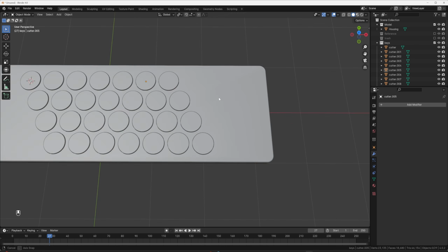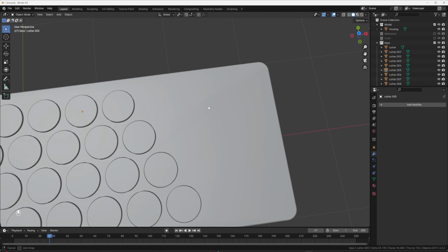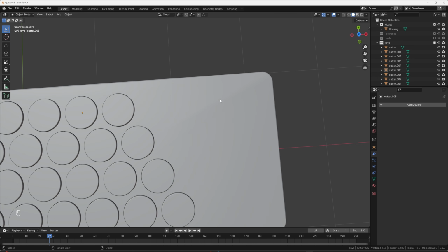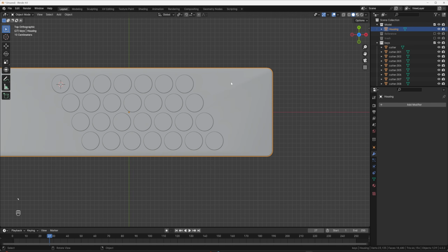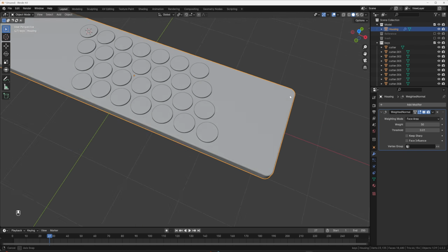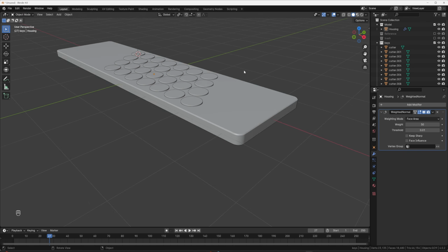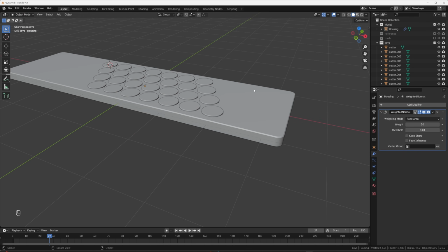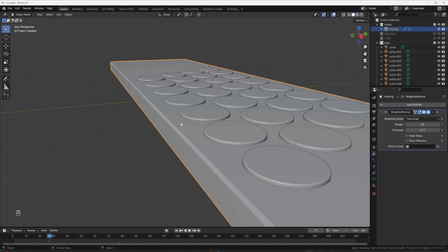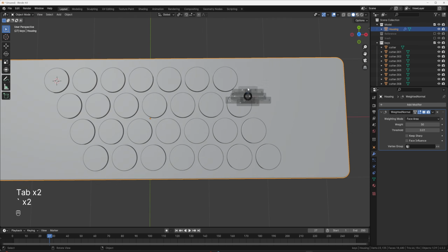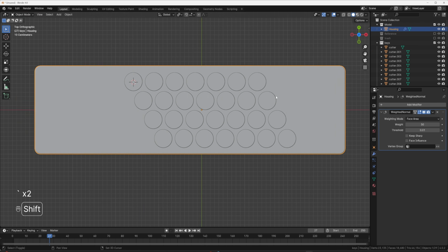And then you also may see a little bit of a shading error. So if you go up here, you can see that there's an issue. This is a flat face, but it looks like it has some pinching. One thing that we can do to fix this is if you click this and go to the modifiers and do W for a weighted normal. I don't understand all the math on how this modifier works, but for things where you cut booleans out, it is a lifesaver. It will completely fix most areas as long as you have bevel supporting edges on all your edges. So now you can tell there's no shading errors on this piece.